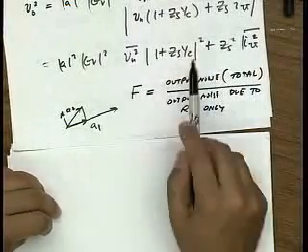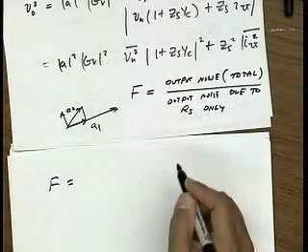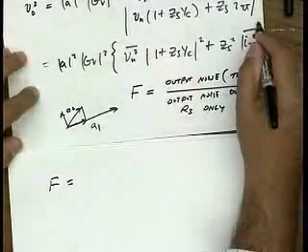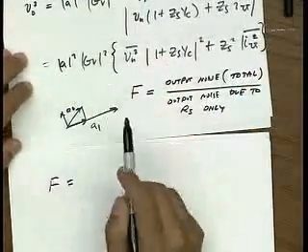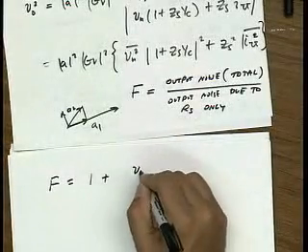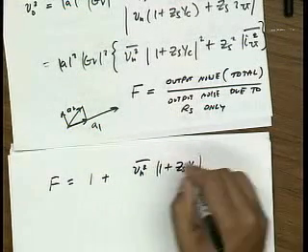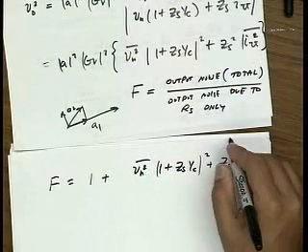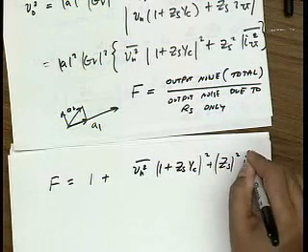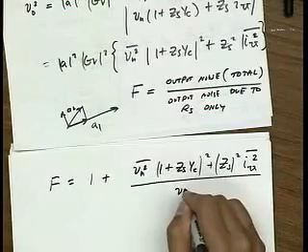So I know that term is going to give me a 1 when I divide out. If I divide out these terms, these all cancel out because they are in common, this leading coefficient. And so what I get is 1 plus Vn squared times |1 + ZS YC| squared plus ZS squared In squared, divided by the noise of RS.